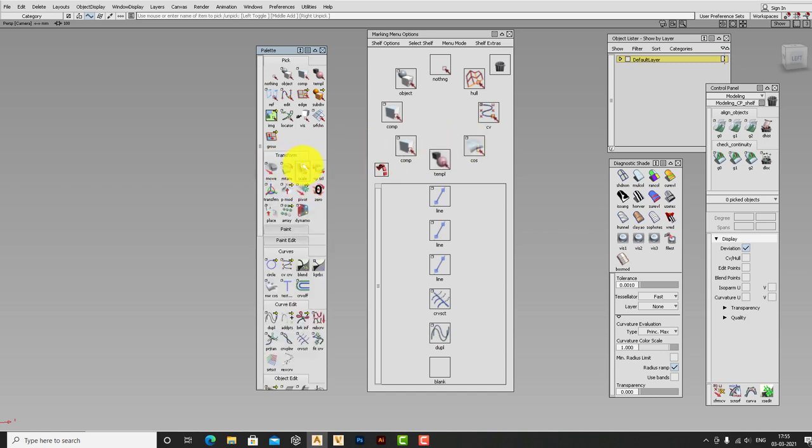Similarly we have transform tool options like move and all. So what we generally do is in first click we keep all the selection items or starting items like curves, how to start with, and middle click is generally for the editing tools. All the editing tools are kept in middle click like move, scale, rotate, set the pivot, query editing. Query editing means editing the command you have used, and others like trim, untrim, aligning and extending tools.